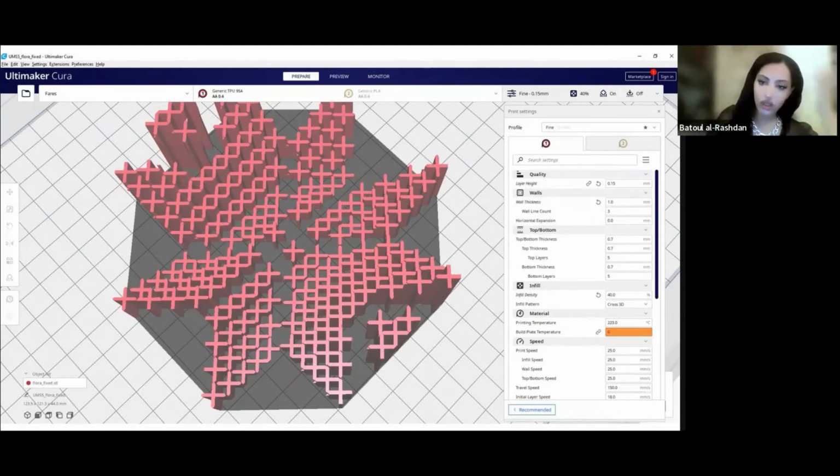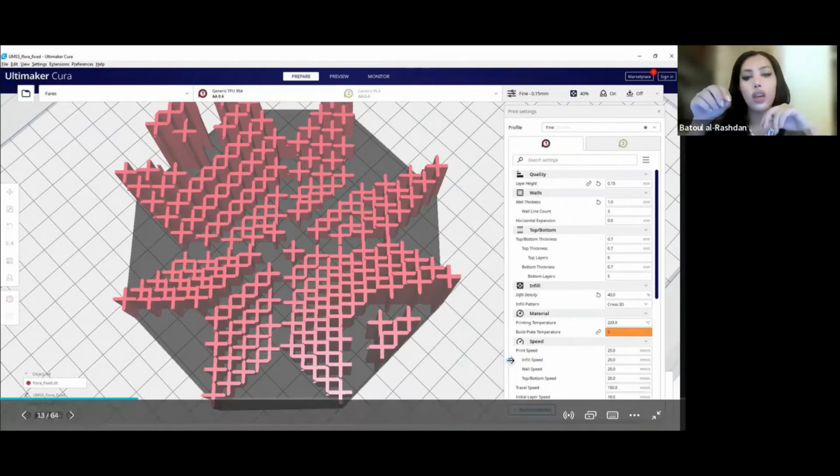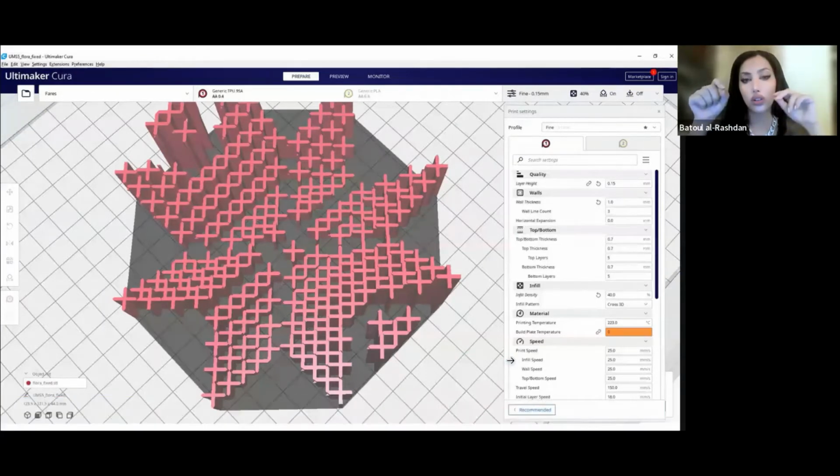You set it depending on the case and the material. You usually set the material so the extruder knows the temperature of the material, so it knows when it melts. It starts melting it based on the temperature at which that specific material melts. For example, TPU and Filaflex are printed at a higher temperature than PLA. That's why it's important you know the material and the temperature at which it melts. You usually read the data sheet of the material. I'm not gonna get more into the technical details. We can move on.